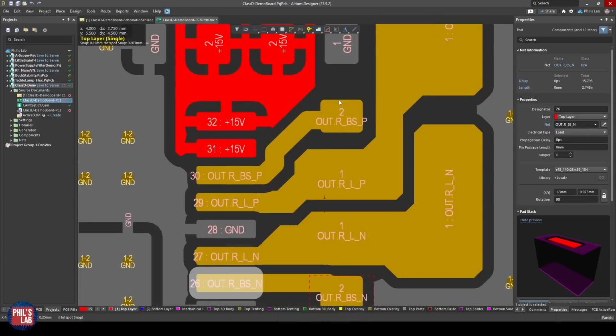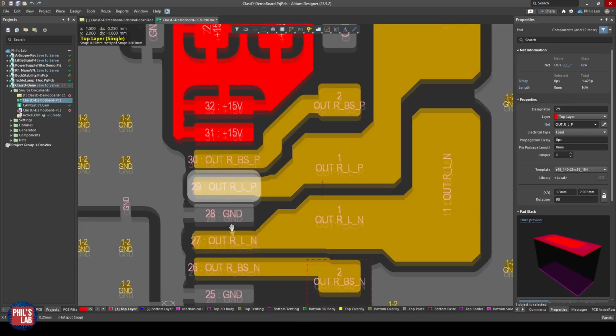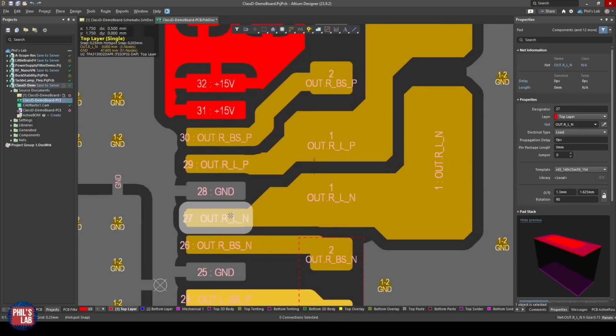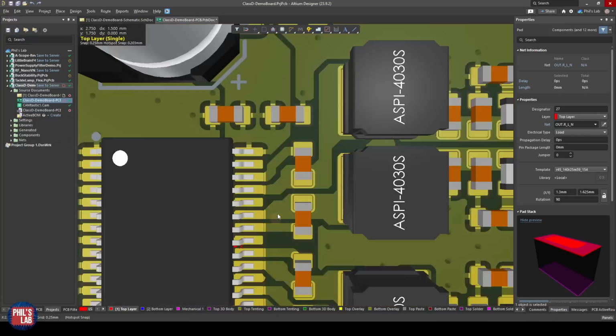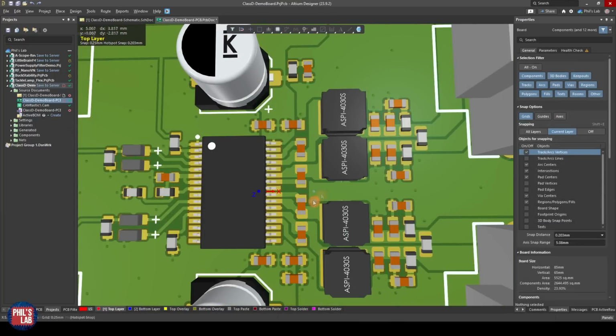The bootstrap connection, for example pin 30, doesn't actually carry particularly much current, therefore a sufficiently sized trace, so typically the same width as the pad of the IC, a short wide trace directly into the bootstrap capacitor. The switch node, however, for example switch node 29 or switch node 27, we should think of very similarly to a switch node in a buck converter, meaning we want short connections. We don't want to make our connection arbitrarily wide because that adds unnecessary capacitance, and we always, of course, want to keep loops small. Keeping loops small means typically placing components sensibly close to the relevant IC and pins.